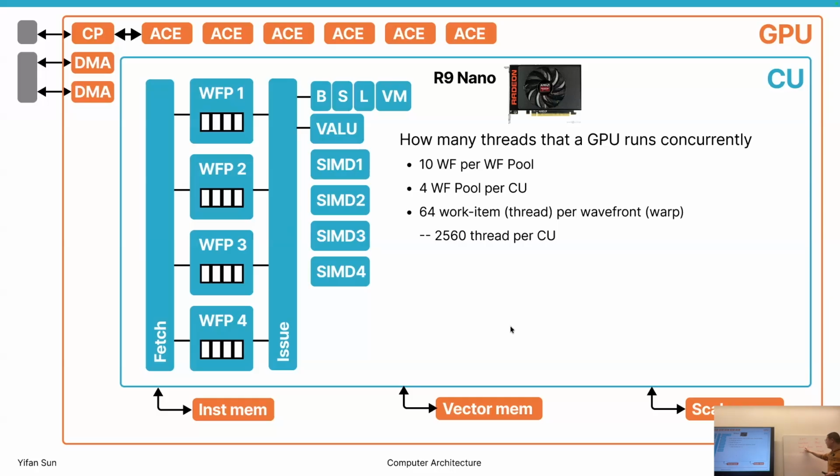So basically, other than wavefront, I pretty much use NVIDIA terminology. And another thing, this is called CU, compute unit. This side is called streaming multiprocessor. AMD calls the data storage LDS, local data share. NVIDIA calls this thing shared memory. Okay, some term mapping.